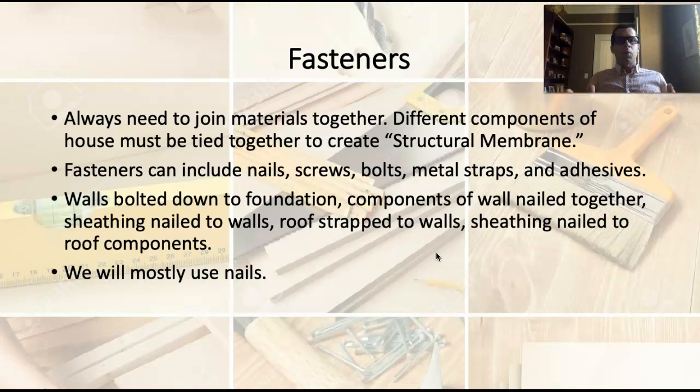Again, we're going to talk more about this, but let's start at the foundation. We've poured a big piece of concrete in the dirt. All of the weight is going to go down to that concrete and then get distributed back to the dirt. Our concrete that we pour is going to have bolts sticking out of it. We're going to drill holes in the floor and actually bolt the floor system down to the foundation.